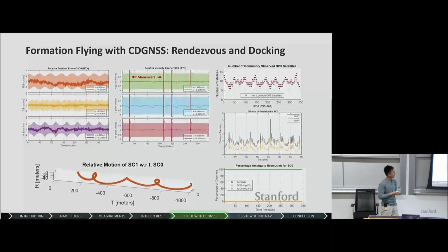All right. In which this rendezvous demonstration took about 5 to 6 hours, so it was close to about 4 orbits maybe. And the docking point was not at 0 because the ISS was actually pretty big. So I manually computed what the docking point would be, and I just set that as the rendezvous point. And this was just running digital statistics to see that it could actually perform moderately well under the influence of multipath noise as well.